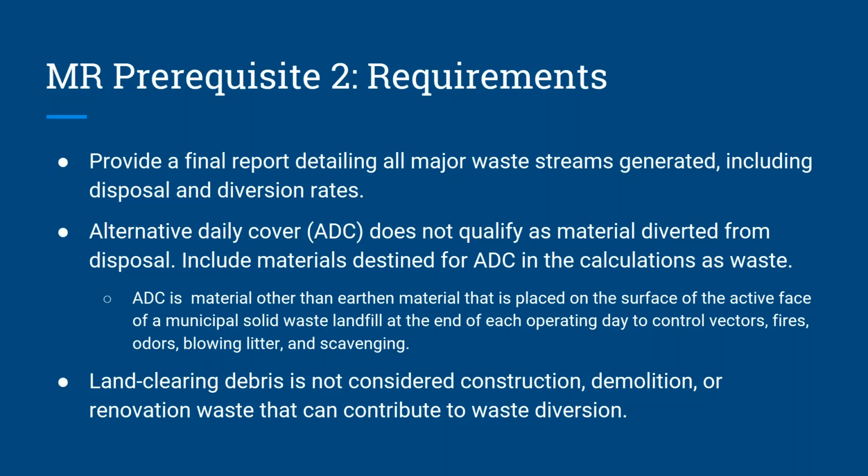Alternative daily cover, or ADC, is a material cover other than earthen material that is used to cover waste at the end of an operating day to prevent the spread of material waste and does not constitute an alternative form of waste diversion. Land clearing debris is waste generated from the removal of vegetation or site preparation for land improvement. As such, ADC and land clearing debris do not qualify as diverted material under LEED specifications.